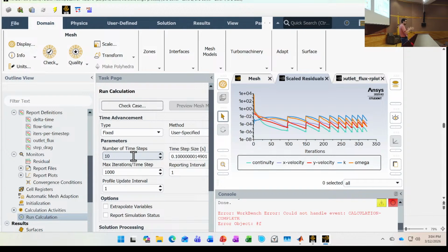So the computer is essentially saying, oh, 0.1, fine, let me try a first shot of 0.1. What's my error? Oh, too much, don't do that. Okay, let's try 0.05. Oh, maybe too much. 0.01, right? It keeps going until it gets to a conserved residual.